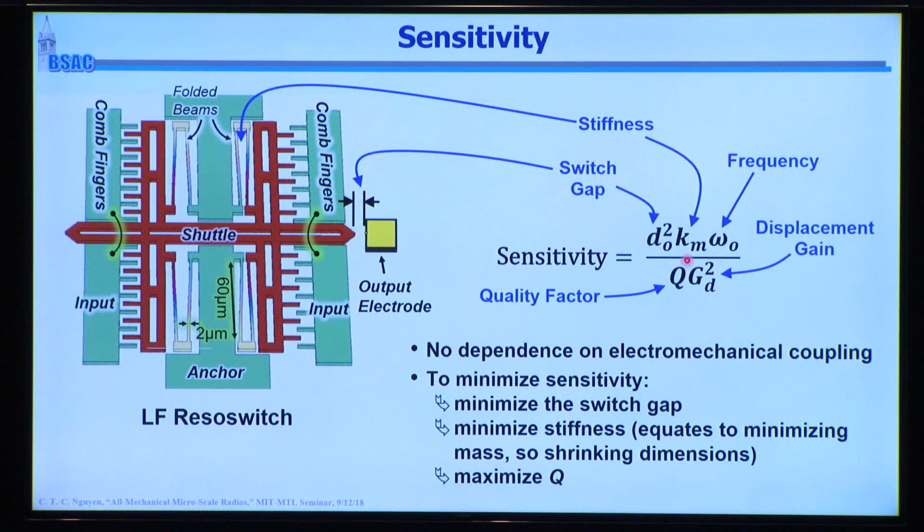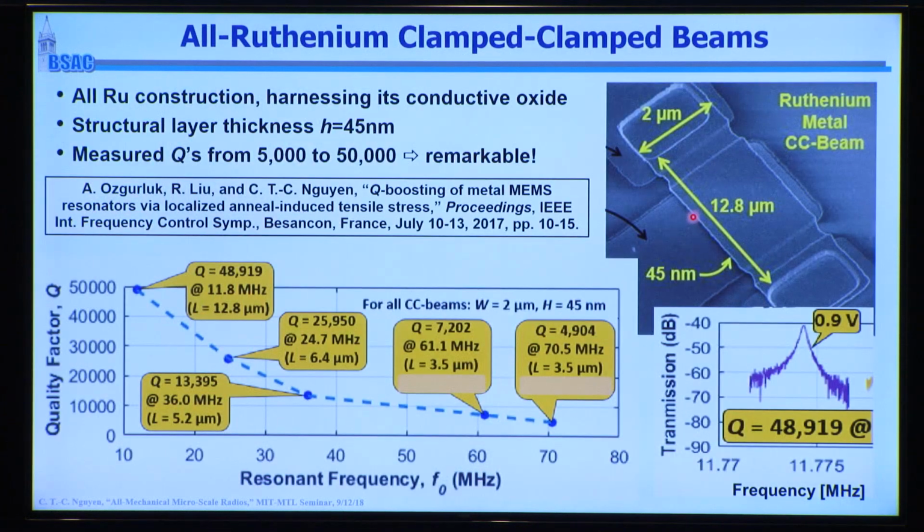Quality factor, and a displacement gain just means, I haven't shown this, but you can actually create a mechanical circuit to create displacement gain as well. But you can play around with these factors here, and it turns out that you can reasonably work at frequencies up at 100 megahertz here. Your sensitivity will probably not be minus 100 dBm without some help with some circuits on this. But you can work there, and if we can work just at 1 megahertz, which is the AM frequency, then we don't rely on this gigantic antenna out in Colorado. We can have something in every city that can now transmit something to all sorts of things. And you could put these things, since they don't consume power while listening, in anything. Your book, things on the shelves of stores and that sort.